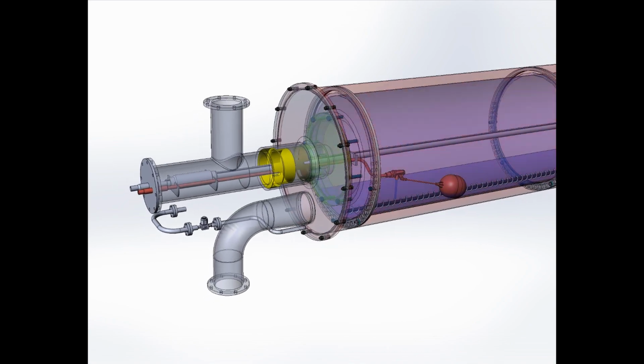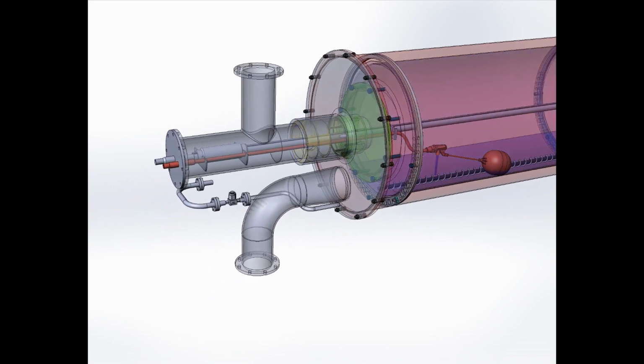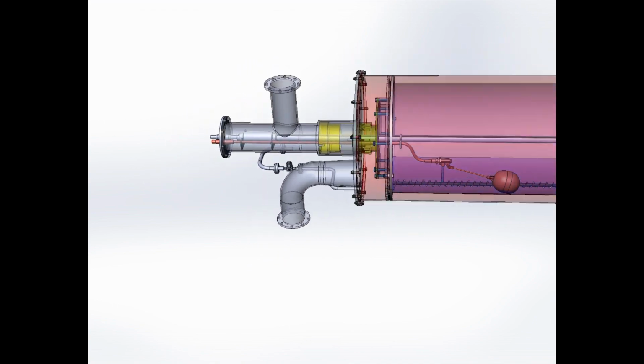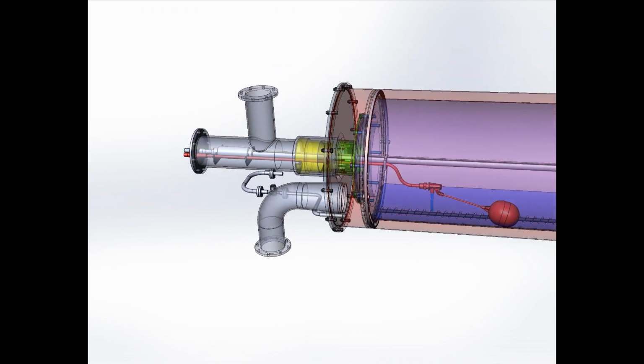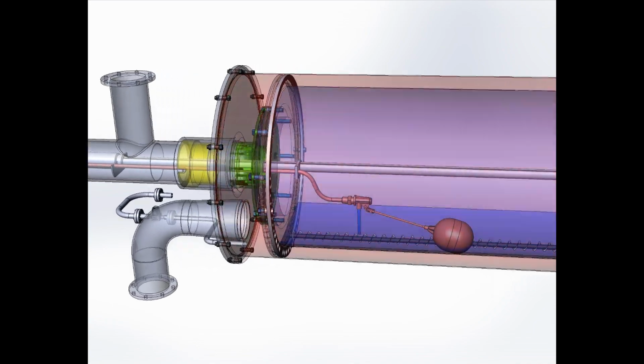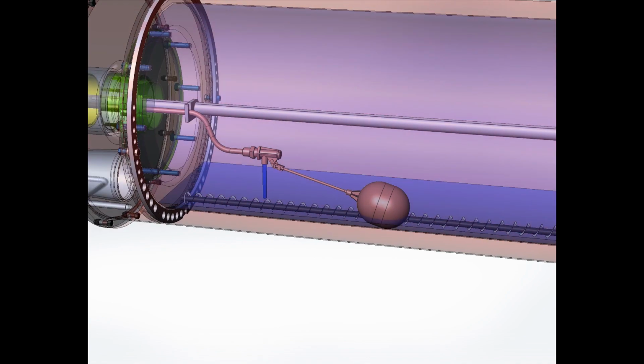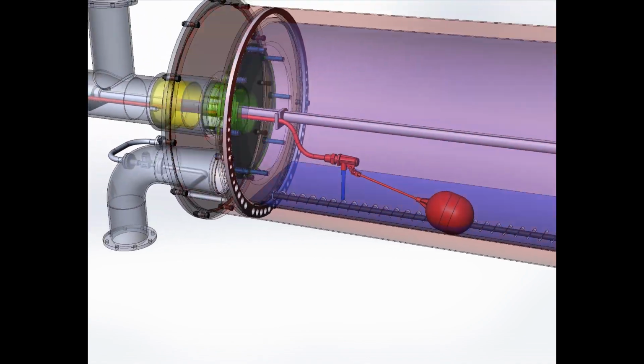The efficiency of solution evaporation is ensured by the mode of film evaporation from the wetted inner surface of the rotating drum. To do this, a constant liquid level must be maintained at the bottom of the drum. This purpose is served by a float valve, which automatically regulates the flow of the solution supplied for evaporation, for example, seawater.